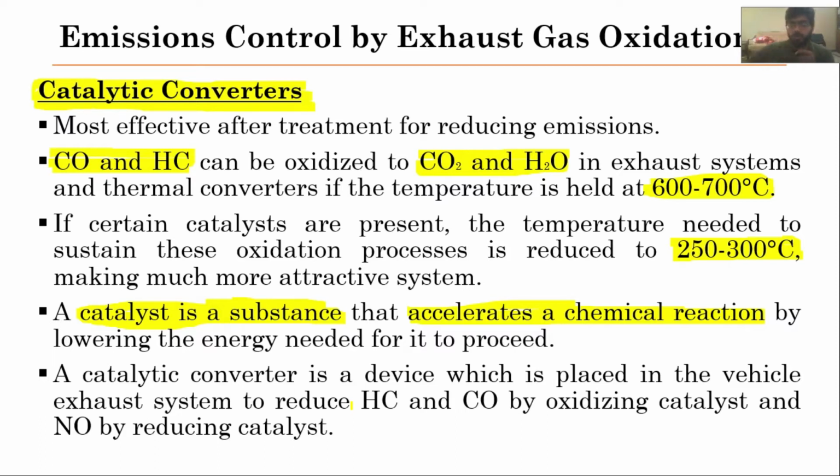Not only are these catalytic converters oxidizing the unburned hydrocarbons and carbon monoxide into carbon dioxide and water vapors, they are also converting these nitrogen emissions, reducing them to form nitrogen molecules.